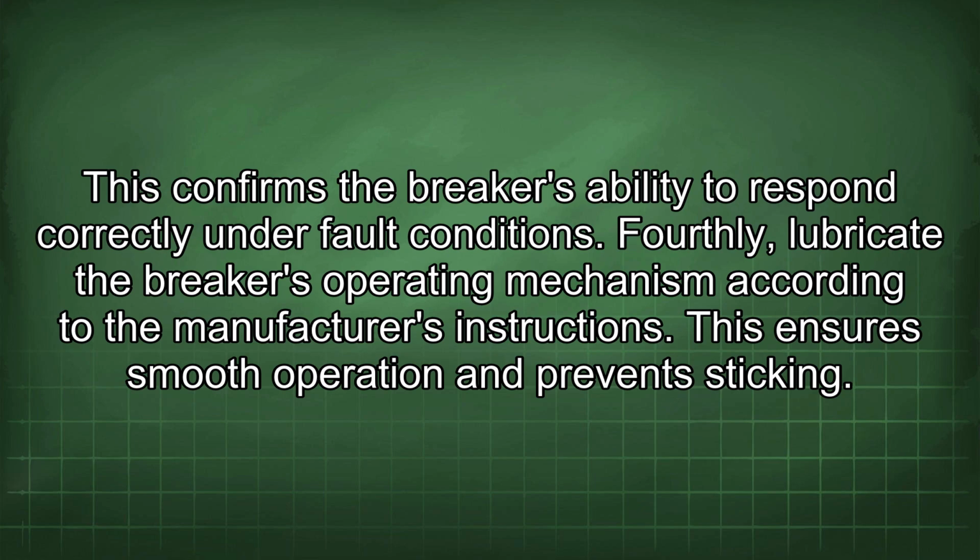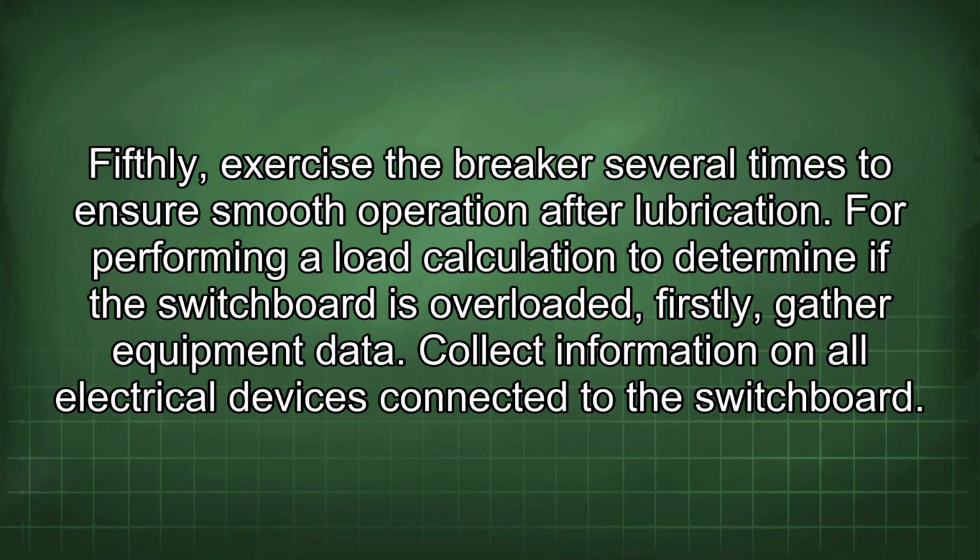Fourthly, lubricate the breaker's operating mechanism according to the manufacturer's instructions. This ensures smooth operation and prevents sticking. Fifthly, exercise the breaker several times to ensure smooth operation after lubrication.